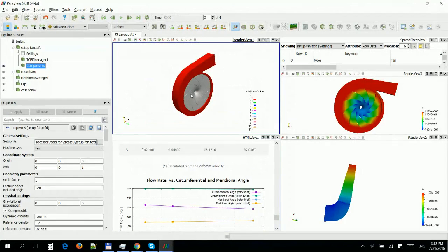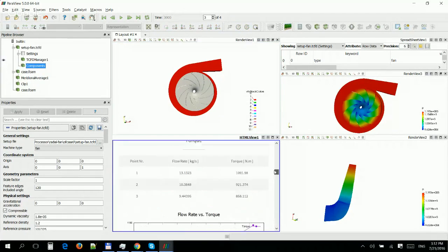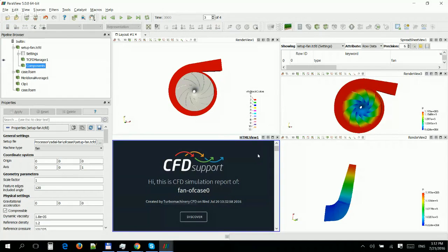Okay, so we have the fan tutorial here. You can download it on our website. The aim of the fan designer is always hunting the pressure ratio, flow rates and torques, which together create the efficiency. Finally, the efficiency. What is important at the beginning all the time is that each Turbomachinery CFD simulation has its surface model and configuration file. So the inputs are the surface model